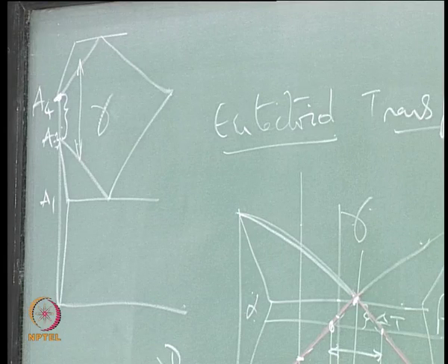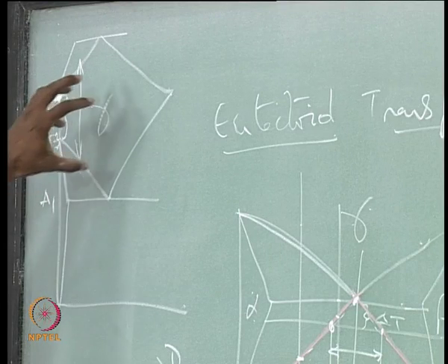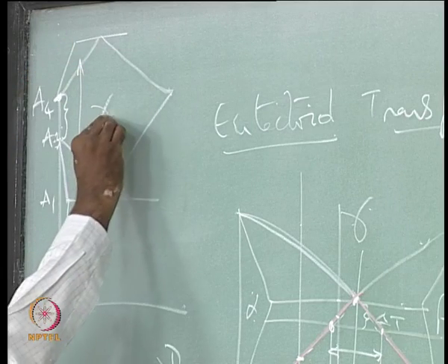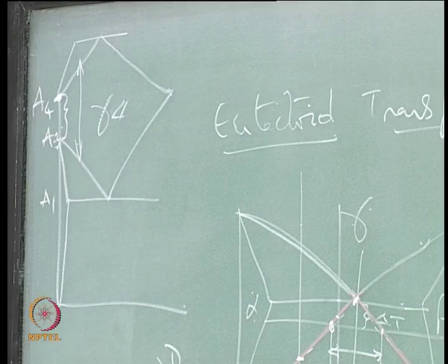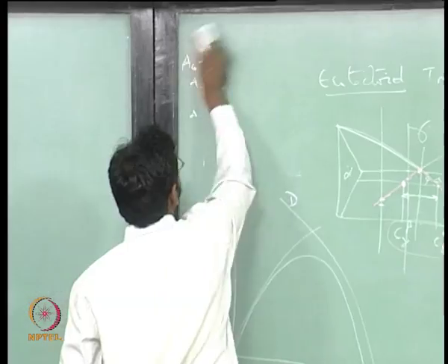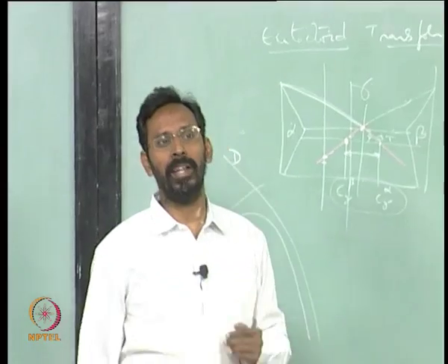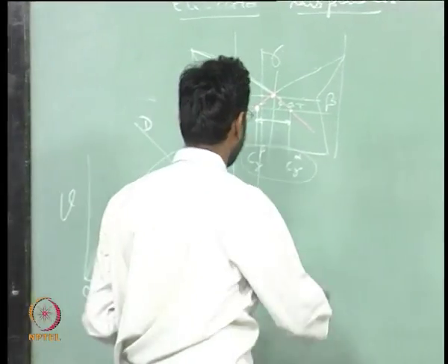And the same thing now, if you add the chromium, you will see that this whole gamma field shrinks to a small domain like this, around 18% or so, or 20% if you add. And nickel, if you add it, this goes down further, which is an austenite stabilizer. So any austenite stabilizer will keep on shifting it down. So you can know from that how each one stabilizes anyway. So these things also are decided by the composition, so we need to know about it, okay.